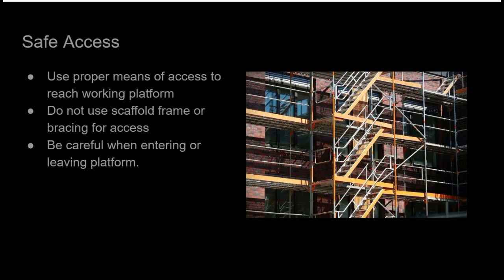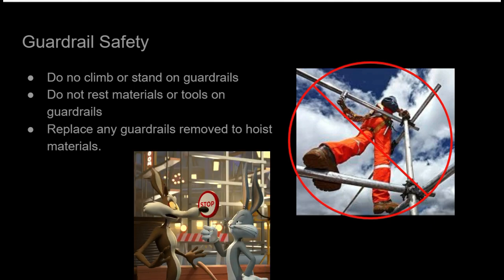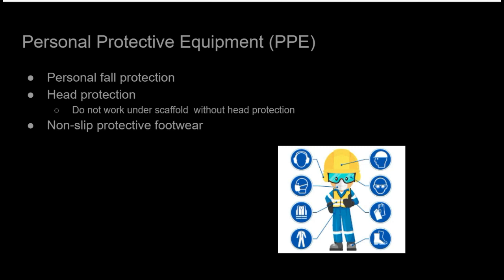Be especially careful when entering or leaving the platform. Guardrails are in place to protect you from falling. Do not climb or stand on guardrails or rest material or tools on them. If you remove a guardrail to hoist materials, replace it right away.